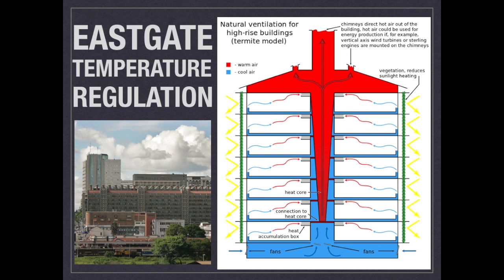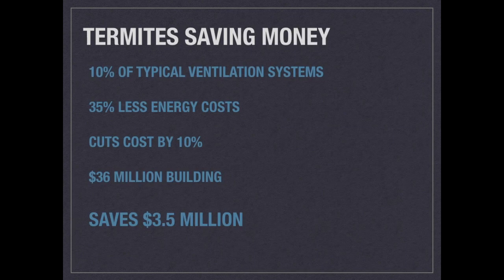Then at night, the cool air from outside is allowed into the bottom of the building, and it starts the convective flow that vents the hot daytime air through the roof vents. The cool air from the night is also stored and distributed throughout the building the next day.